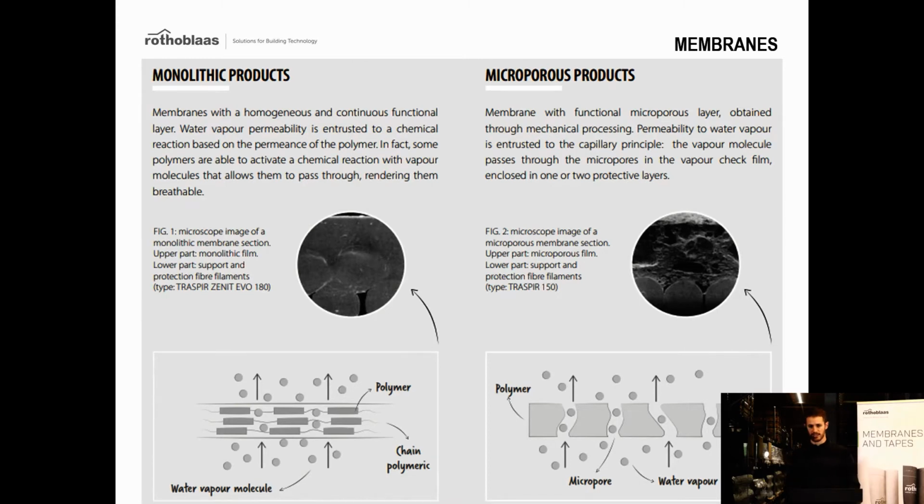Let's say like that. In the microporous products, all the molecules are arranged in a way that there are some very, very small gaps between one molecule and the other. They're not holes, of course, because they are still waterproof, so we don't have holes, but the water molecules, the vapor, can pass through by capillarity throughout these small gaps that are formed.